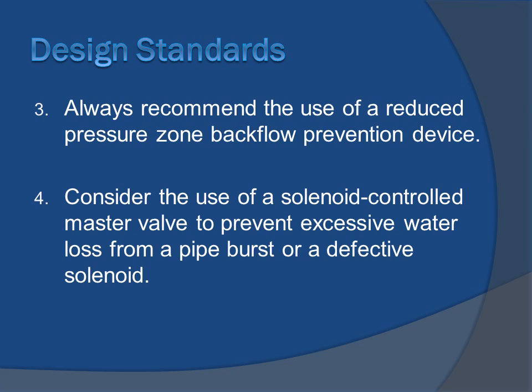So what it would do, say we're going to set the system up at 5 o'clock in the morning. That master valve will turn on at 5 o'clock, and then you might have the next zone come on at like 5:01 or something. But then when the system's finished irrigating everything, that master valve gets cut off so that there's nothing going out to the system. They're saying a solenoid control, but that can also be a hand valve too. I mean, if you had an accident, the guys are digging on a construction site, there's already an irrigation system in place, they're adding on to a house or something, they dig up the lines, boom. Instead of going all the way back to the meter to cut it off, there could be a master valve somewhere that would turn it off.